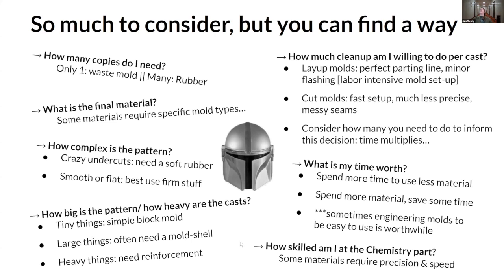It's not going to work. And then another thing under the heading of preparation: if your mold has a defect or something that you simply don't like, every single cast you make from that mold is going to have that defect, and you're going to have to clean it up or change it or work on it in some way.